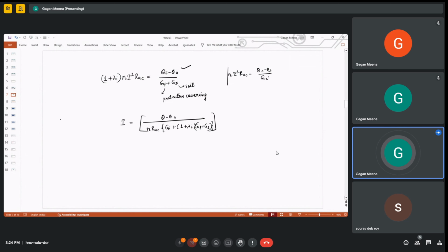And what will be the effect of dielectric loss in this? The effect of dielectric loss will be to reduce this current rating. Because above 66 kV voltage, the dielectric losses are also very significant and they are independent of load current. The current causes an increase in the temperature of the dielectric.